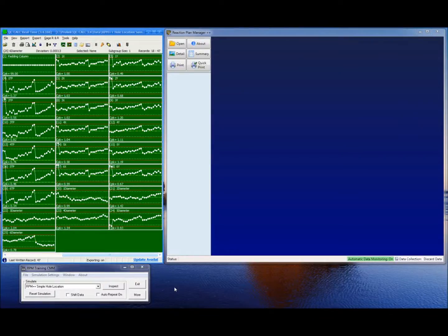In this video, I'm going to demonstrate how to analyze hole measurements. Most parts contain holes. The typical manufacturing process involves a tool machining multiple holes. For example, the mounting surface of a transmission case has many holes machined with one tool. To evaluate this type of manufacturing process, you need to group the holes together and evaluate them as a pattern.